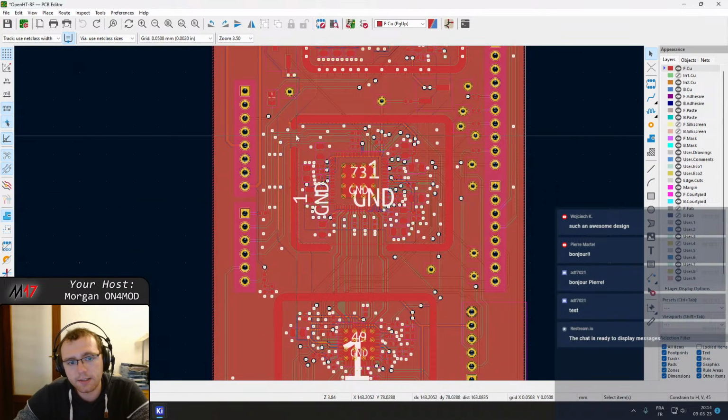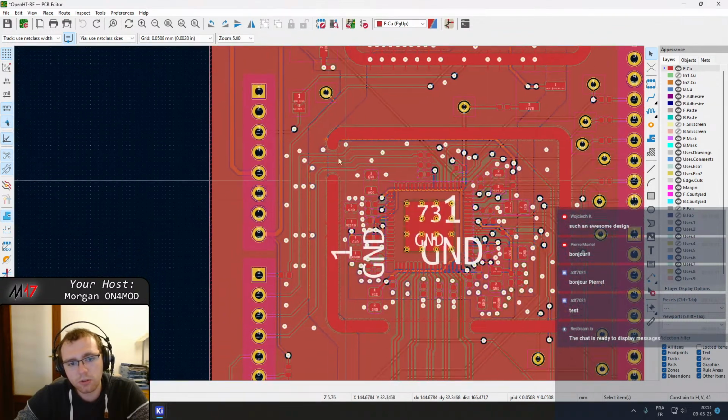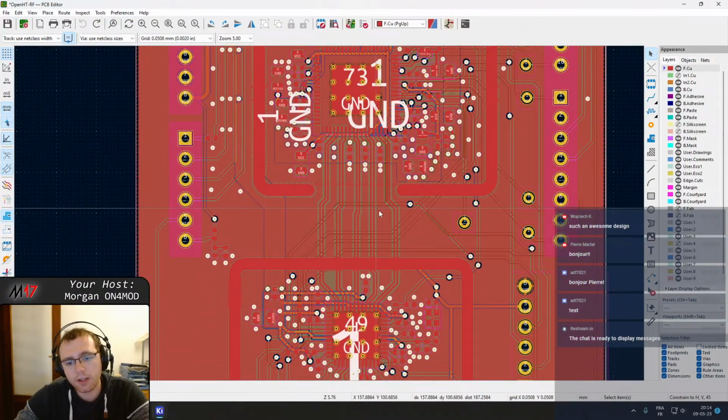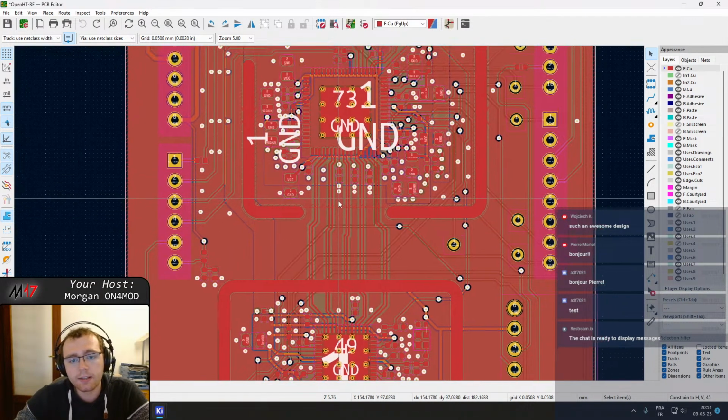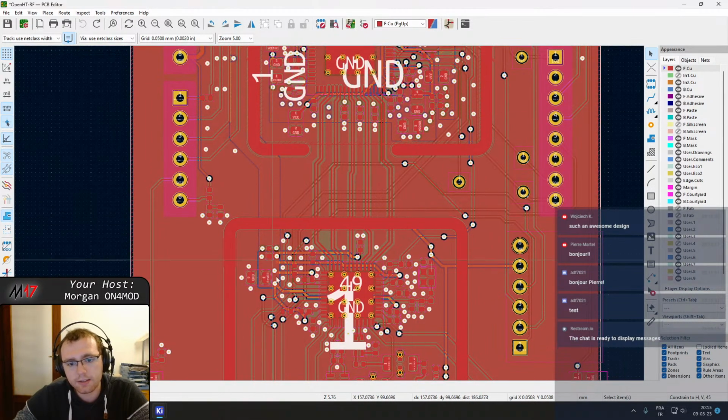You can also see that I made some openings on the shield on the top left and on the bottom. On the top left, because I had some signals that I had to take out of the shield, and of course on the bottom for the LVDS pairs. I really don't want to have any vias in those pairs, because it is going to impact the impedance of the line, and it might make it difficult to go at the required frequency. So like this, it should be perfect.